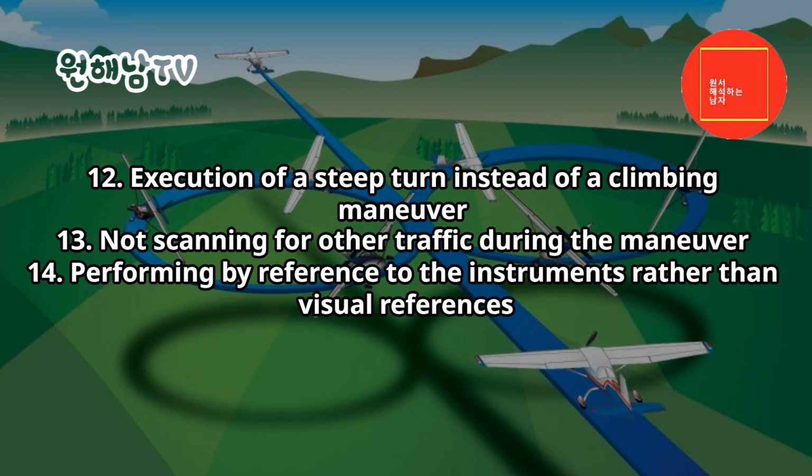12. Execution of a steep turn instead of a climbing maneuver. 13. Not scanning for other traffic during the maneuver. 14. Performing by reference to the instruments rather than visual references.